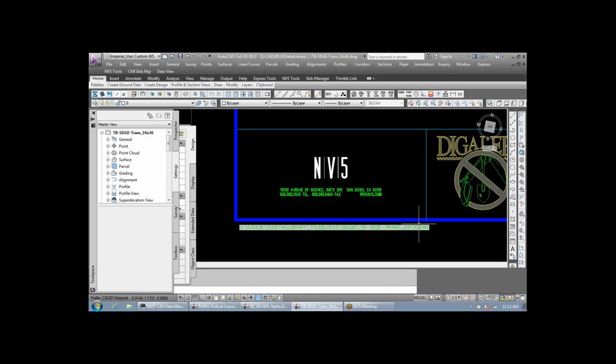The first being, if you do find a need to change the UCS, be sure to change the UCS back to world upon exiting the drawing. Another nice thing to do is zoom extents your drawing. Make sure that you don't have any floating objects out in space. The last thing you want to do is have to chase those down in 10 different drawings. When you zoom extents in your drawing, oh wait, there's this floating pipe out there, and then you clean that up and then you do the same thing, and oh, there's something floating somewhere else. So just be sure to treat your files with respect for others. UCS world, zoom extents, make sure you don't have any floating objects.